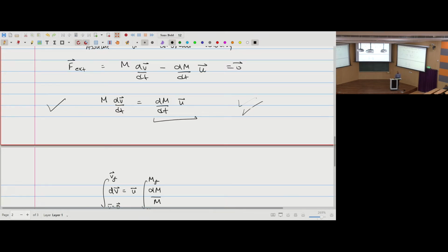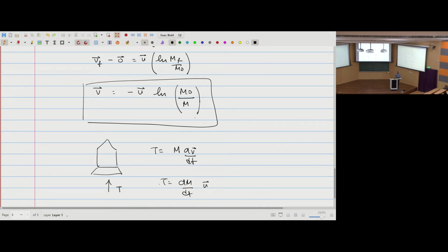But typically, there is a lot of interesting dynamics happening in the rocket, and we have been able to capture that to some extent by taking the effect of burning gases. So once we have figured this out, you can model this system as an external thrust acting on the system. Actually, it's not an external force. It's an internal force because of the interaction of the molecules of gases with the walls of the engine, because there's a sudden explosion of gases. They have high pressure. They apply pressure on all walls except that one ending which is open. So the net effect the gases have on the rocket is to give it a push up.